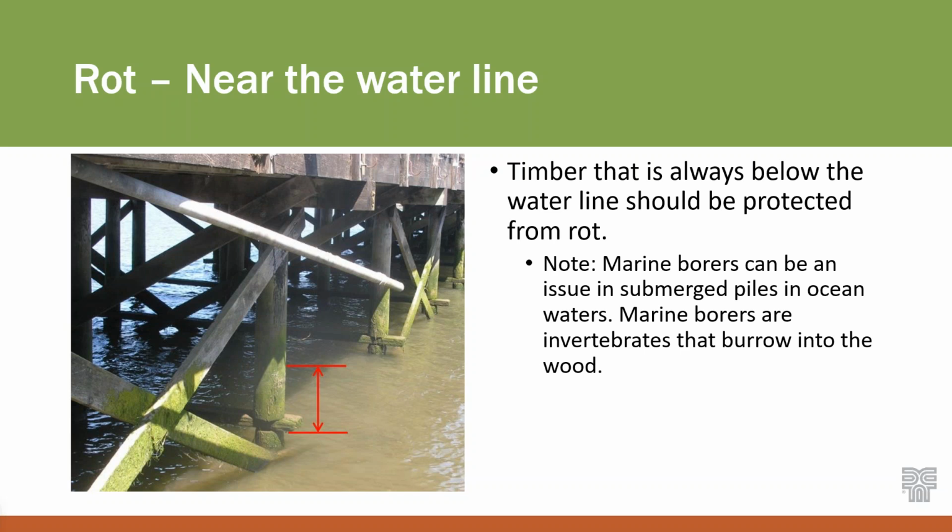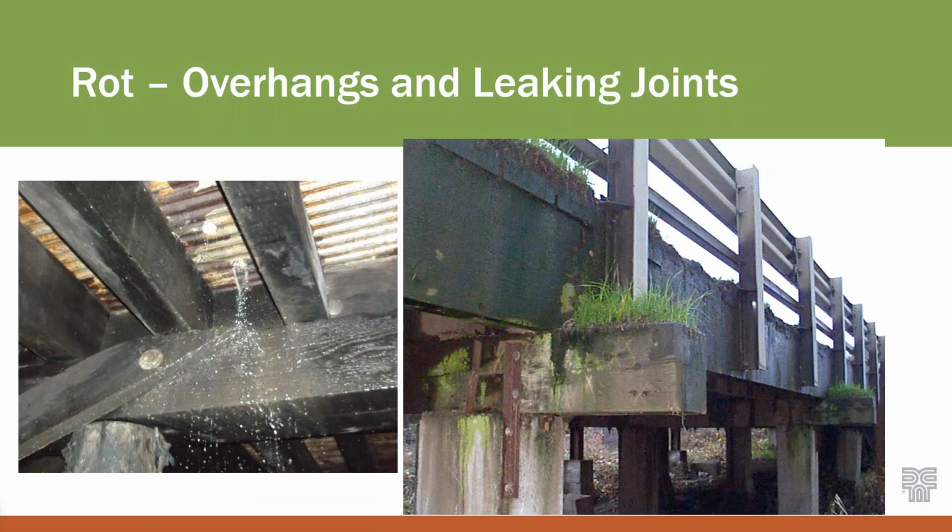One caveat is that although rot is protected in the water, if you're in salt water, marine borers can actually destroy piles pretty quick. So just something to pay attention to. Again, we're not trying to cover every possible case, but these are the common ones that I come across.